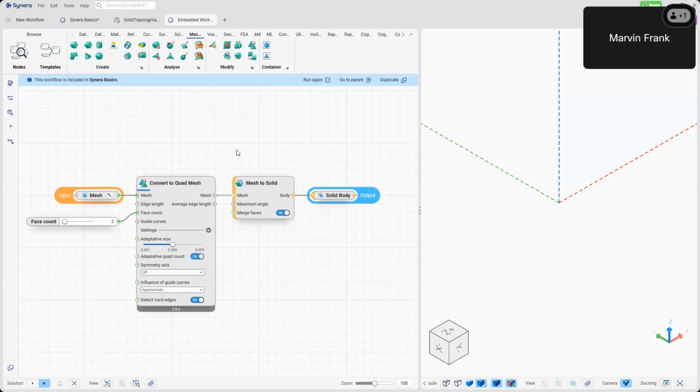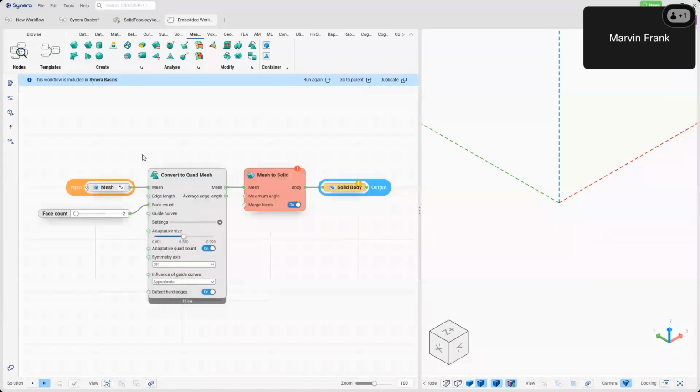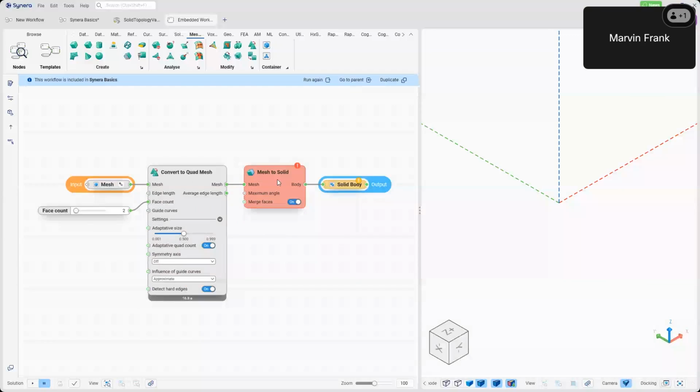No, nice. Okay, so we have created an error. Of course, it's not possible to condense this mesh into 2 faces. So we have a problem here. That's the first thing. So looking in your workflow, you will see these red nodes. When they are red, they have an error here. So first thing you do is reading the error. Only closed manifold meshes can be used to create subdivision models. That means something must be wrong with the input. It's not possible. Mesh Sorter cannot handle it. So that's your first indication.